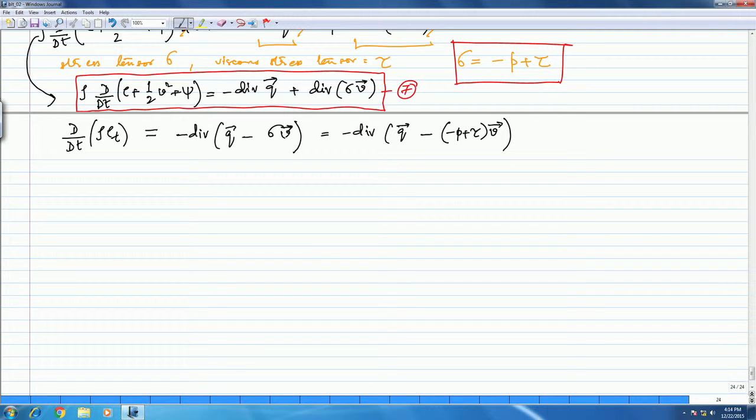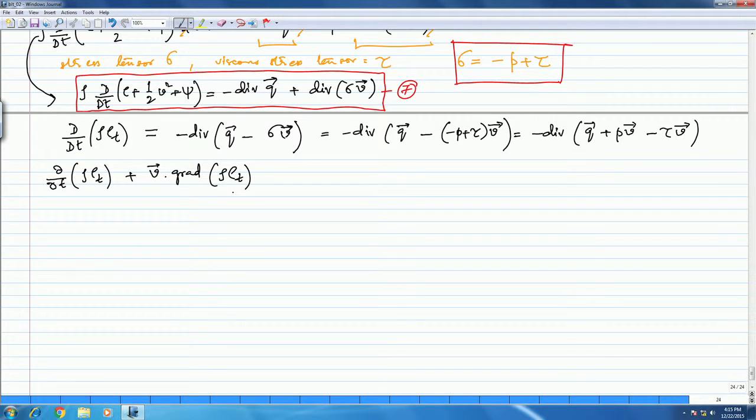Is that right? So, again divergence, this is Q, plus this, minus this. Okay. So, now I am going to expand again the left hand side and write that down as del del t of that, plus gradient. So, this is nothing but the total derivative. So, I am breaking that down. So, this is instantaneous and this is the convective change, in the total energy.